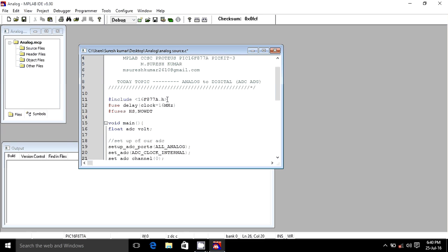So we'll finish it, and we need to add one more preprocessor directive as use RS232, which means the serial port, UART serial port, TTL communication. Baud rate we set 9600.